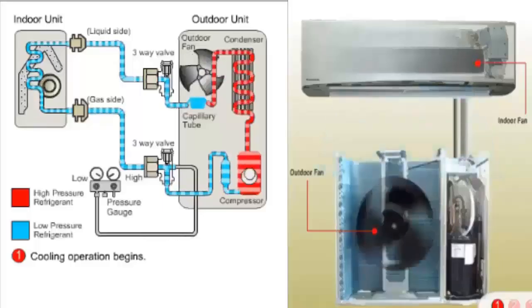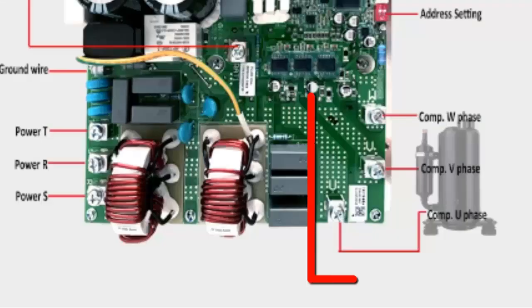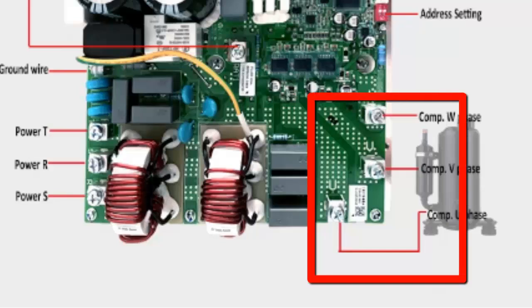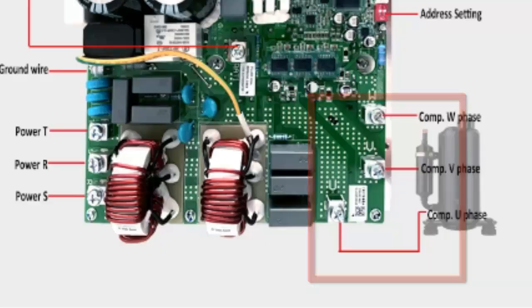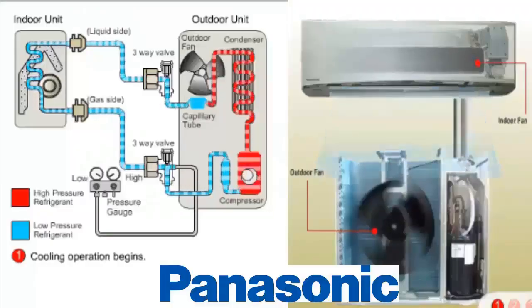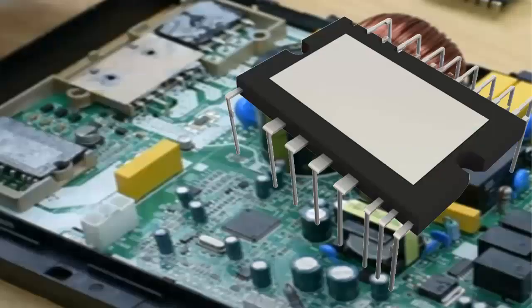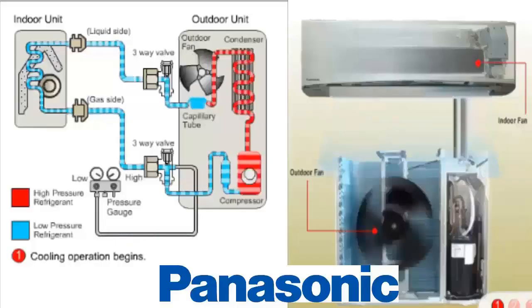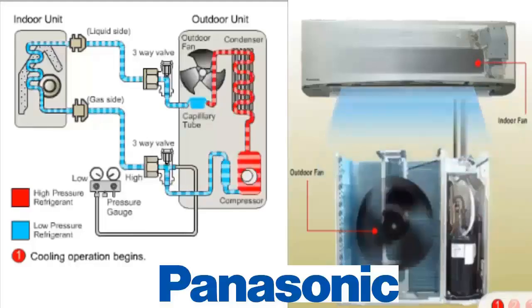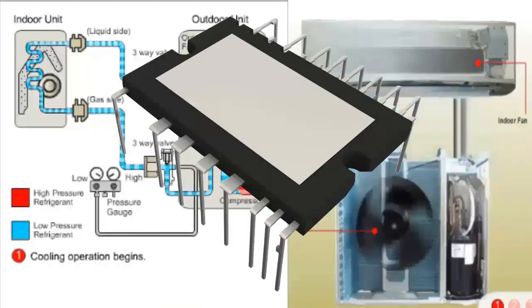6. If the resistance values are correct, locate the power cable output from the board to the compressor and check the condition of each cable. There should be continuity from the electronic board output to the compressor motor input. If everything seems to be in order, focus your diagnosis on the IPM Smart Power Module. 7. To diagnose the IPM electronic module, follow these steps.